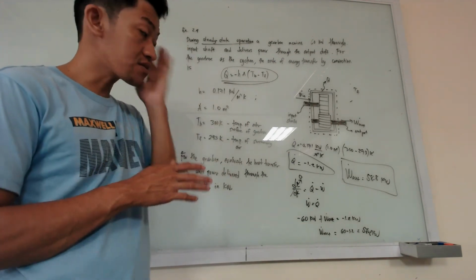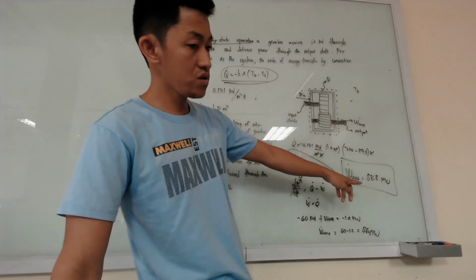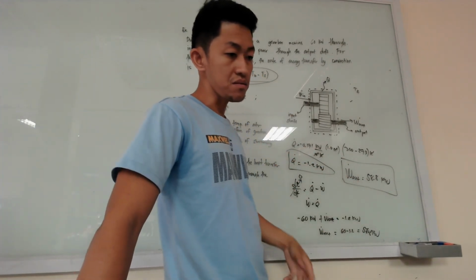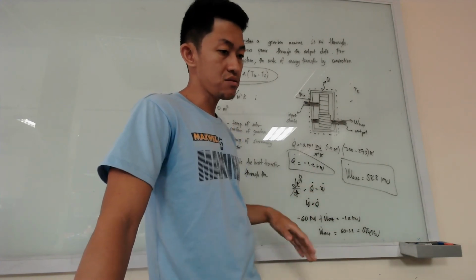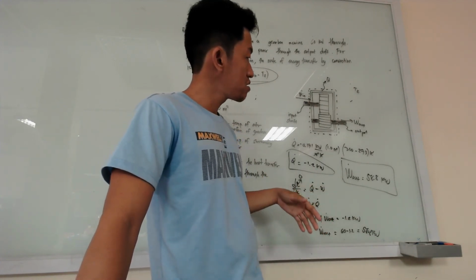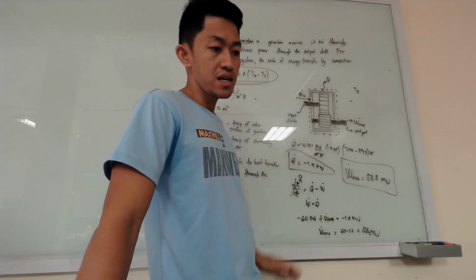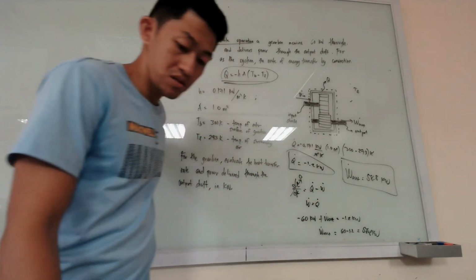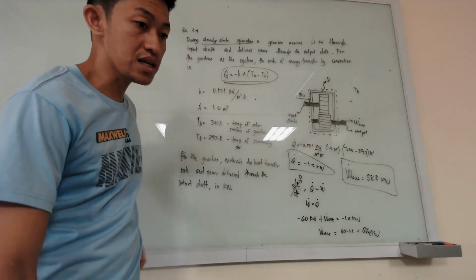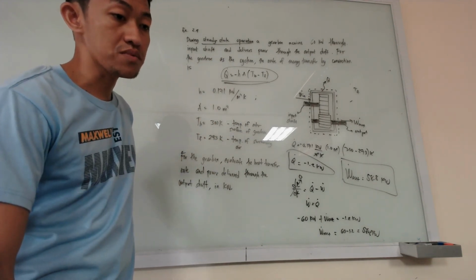Okay, so we can see that from 60 it reduced to 58.8 because of energy transfer by heat, heat loss. Your gears get hot. So there is energy that was lost or went out of your system. So that is it. That is the use of the first law of thermodynamics.